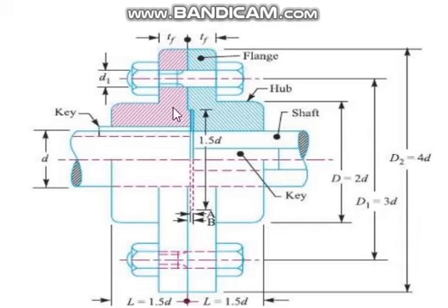So the upper half is cut. That's why it is called a half section. You see one key is here and another key is here. These two are at 90 degrees. You will see the 90 degrees in the side view.